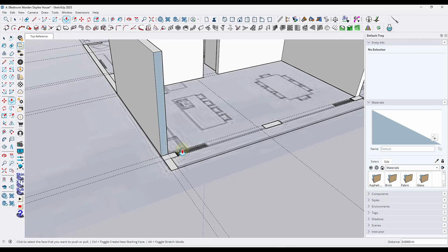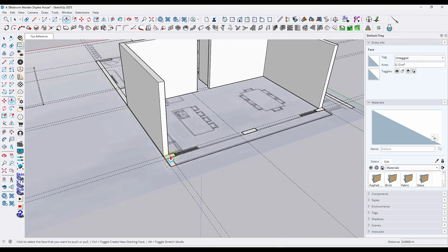So you can see that that makes a mistake here, because that is the previous thing we did, and the previous thing you do in SketchUp always shows up in the next thing you're going to do. So if for instance we take this up to, let's say, 2 meters, and we try to do the same thing here, we're going to get the same thing. Okay, so make sure to undo what you've done. So Ctrl Z is to undo that, and let's try to make another progress forward by using new measurements.